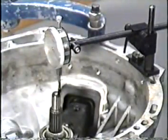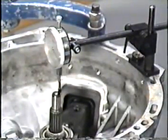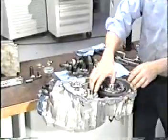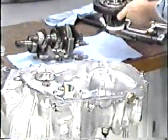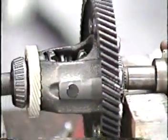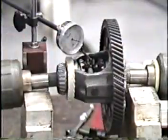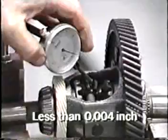End play and preload measurement procedures for the front-wheel drive transaxle are similar to the rear-wheel drive transmission. One of the unique measurements you'll make when reassembling a transaxle is pinion gear backlash in the differential. To measure the backlash of the pinion gears, install the left and right half shafts into the differential and support them on V-blocks. Using a dial indicator, twist the shafts in opposite directions to measure the free play between gears. The readout of the dial indicator should be less than 4 thousandths as specified in the shop manual.